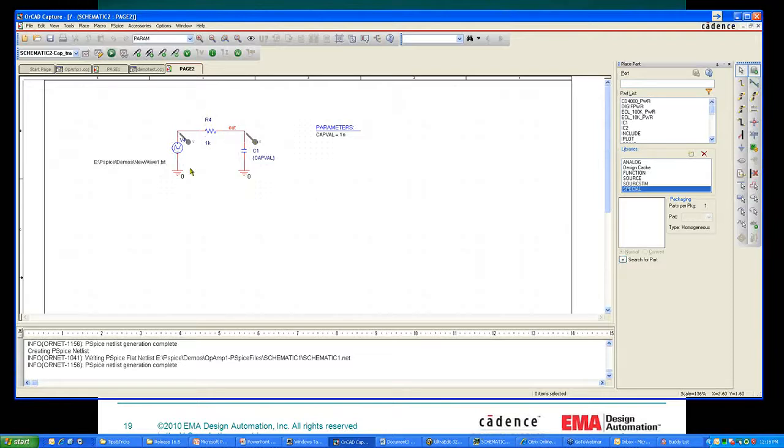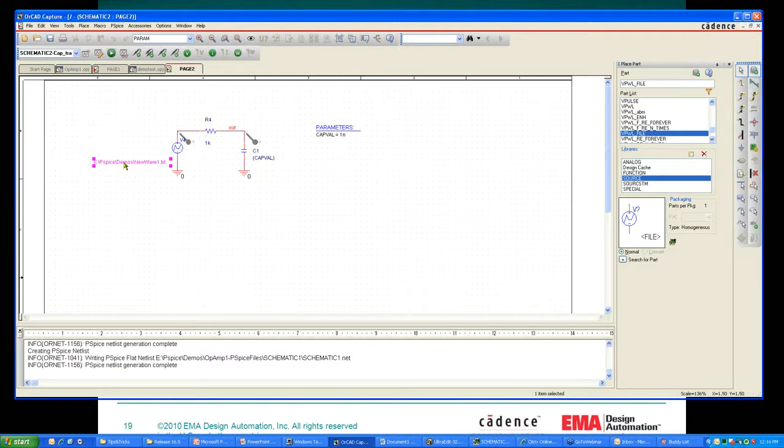And now I'm going to re-stimulate that circuit with the original RC curvature, so that the RC charging response now will have a little bit different, kind of a slower RC curve and whatnot. This is just an example of how you can actually drive a circuit with a new waveform file. So you find this particular source. This is a V-pulse or V-pulse piecewise linear file. That's the component that I'm using. And basically, you put that in to drive your circuit, and then essentially just create this link. It'll include a parameter link to the actual text file that you're going to stimulate it from.